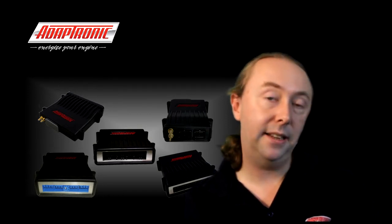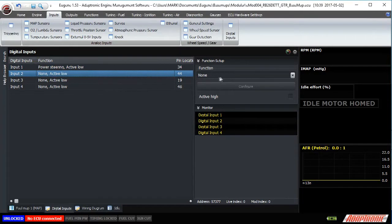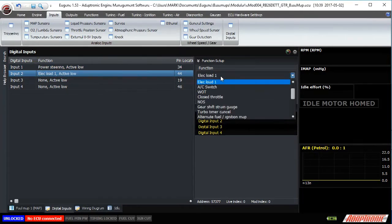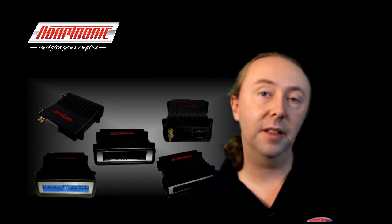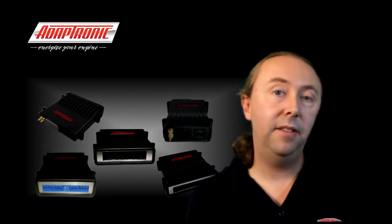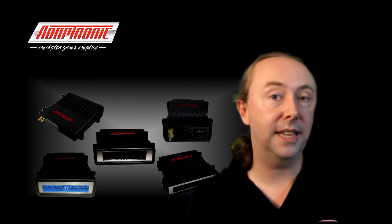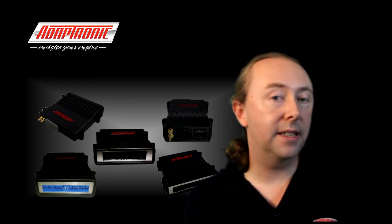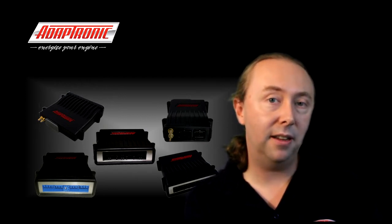Now another example is a headlight input. Generally with headlight inputs, the input actually goes up to 12 volts when the headlights are switched on. So that again needs to go into a digital input on the ECU. And then you can select that as electrical load 1, for example, but set it as active high instead of active low. And then it'll come on when the headlights turn on. So when any of these electrical inputs or the power steering or the air conditioner inputs are active, the ECU will increase the target idle RPM to be the new target when on value in the idle up page.